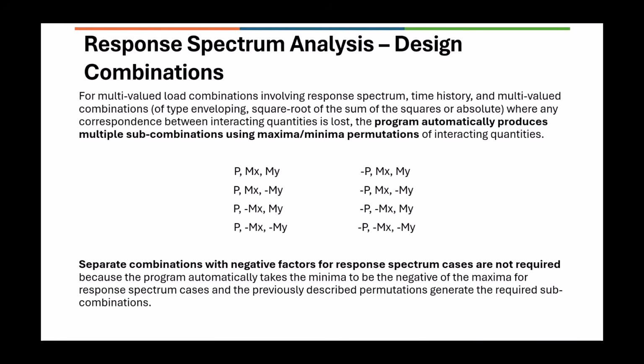So when you see, let's say, a DCon3 load combination, which is by default dead load 1.2 times, live load 1.2 times, and seismic 1.2 times. If you take this particular combination, you will find under the design force, you will see DCon3_1 to DCon3_8 for each member, and then there will be combinations following this sign convention.